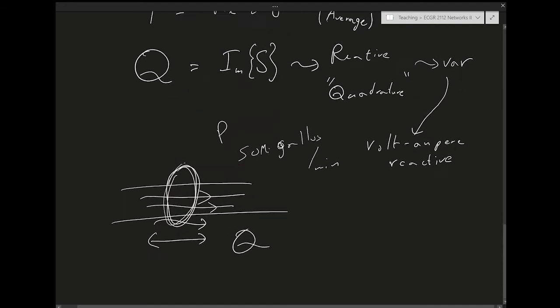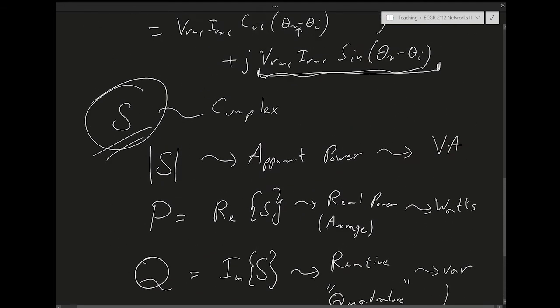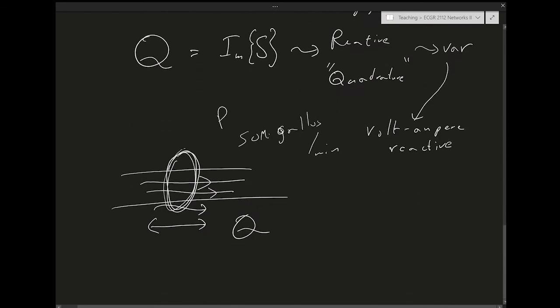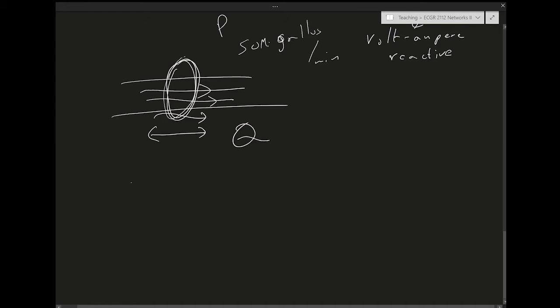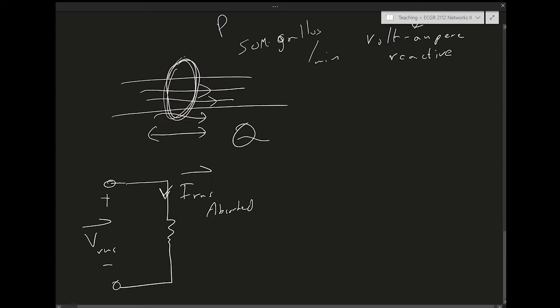Okay. So let's tie this complex power concept to all the basic circuit elements that we know, right? So let's start with the resistor, and let's apply the sign convention for voltage and current. Remember, the sign convention is if the voltage is positive, the current flows this way. This is the sign convention that allows us to calculate absorbed power in the element. Because if we use this convention and whatever power we calculate turns out to be positive, that tells us that this power is being absorbed in the element. If whatever power we're calculating turns out to be negative, using this convention, this tells us that this power is being supplied by the element.